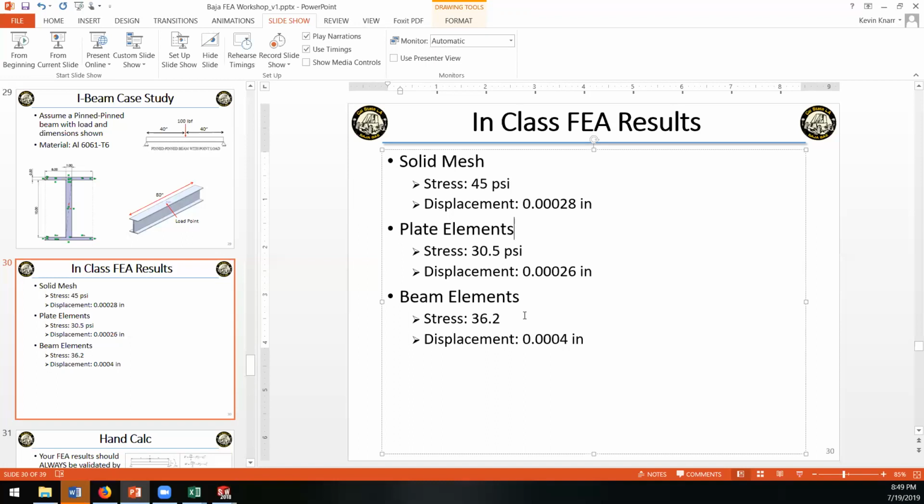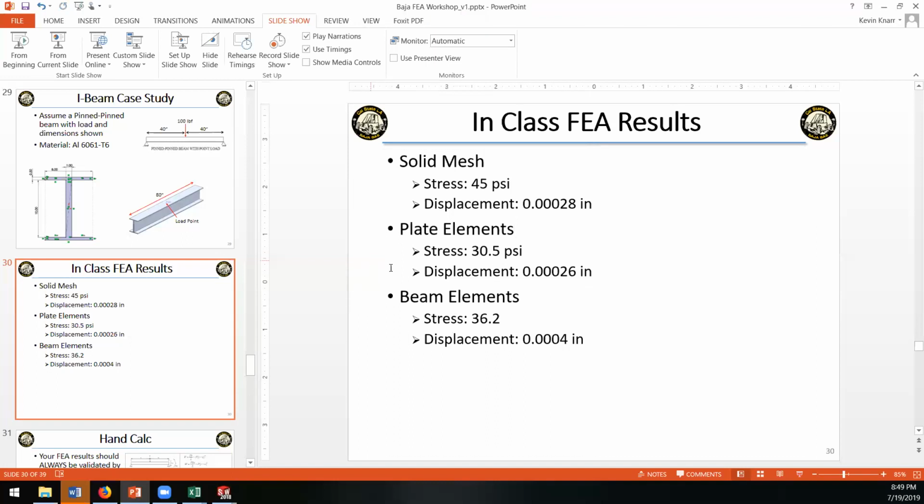Yeah, right. That's the hard part about a solid mesh, right? You're trying to constrain nodes that can have 3 degrees of freedom, instead of a joint where it's a perfect joint simulation. So it's really hard to constrain and put loads on a solid mesh. It's pretty hard to do that properly. You can put things like I did, like rigid members in, and there's other ways to do it. But in SolidWorks, I see a lot of errors due to the solid mesh and bad elements and just the loads and the boundary conditions.